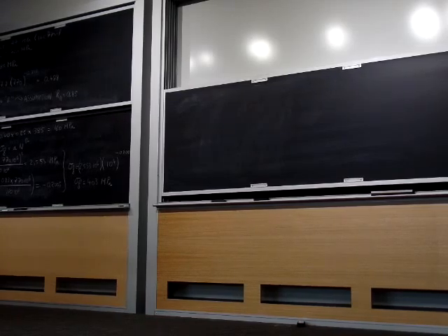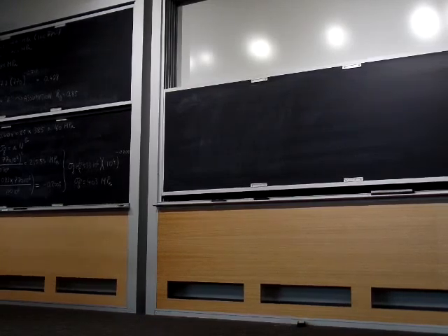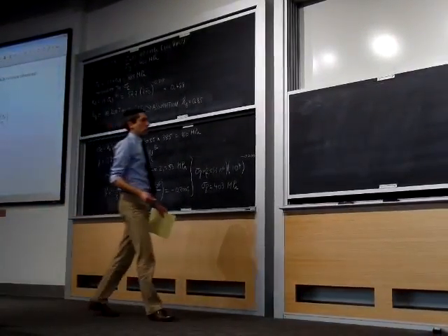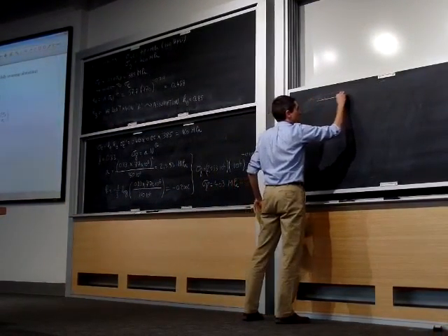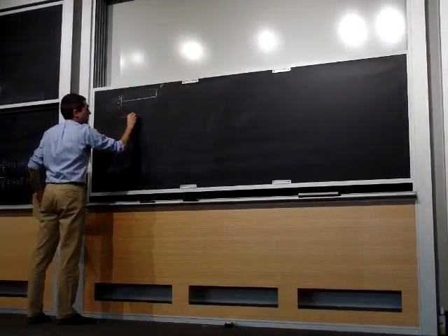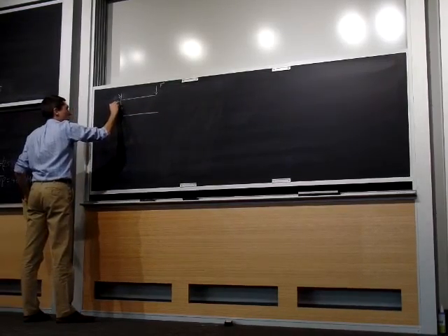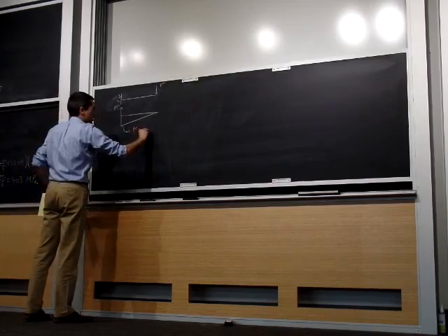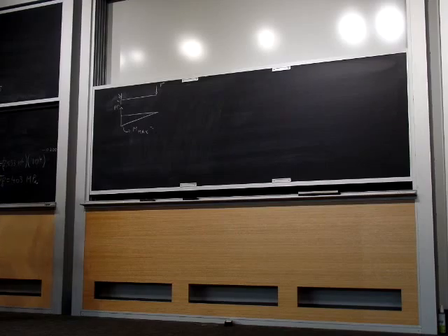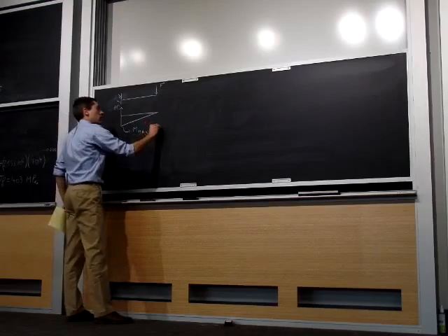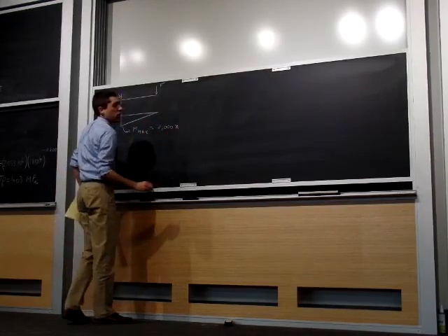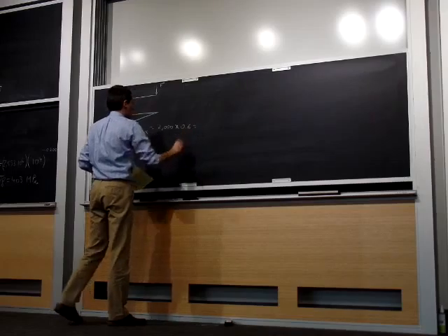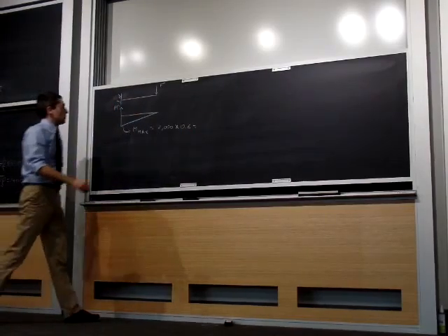Okay, so now we got to start working on our denominator there, sigma A. We need to calculate sigma A, and so we have this cantilever beam here that has a load F. So let's draw our moment line. Alright, so our moment line is going to be a triangle, where this is our maximum moment. And our maximum moment is going to be the force amplitude times the leverage arm, so that's going to be 2,000 times the leverage arm of 0.6. And so that gives us 1,200 Newton meters.